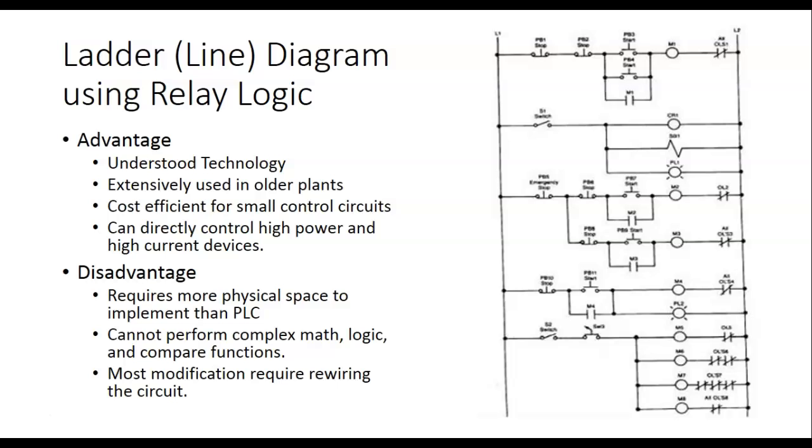So everything is not going to be a PLC. It always boils down to which is more expensive. So if I can do it with relays and I can do it for a lower price, then it's going to be relays. If I can do it with a programmable controller plus relays, you're probably never going to get into a situation where you're not going to have these relays.